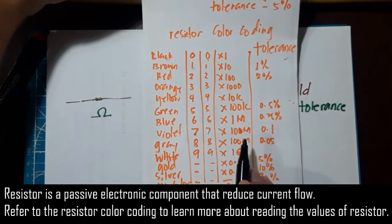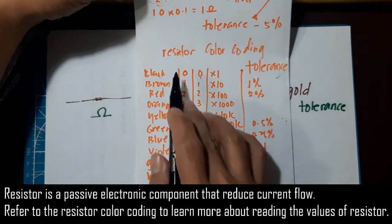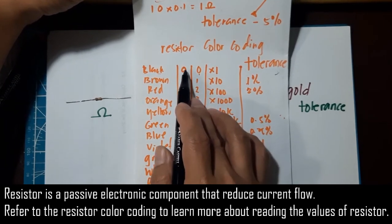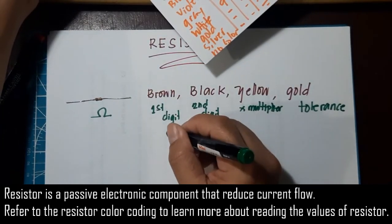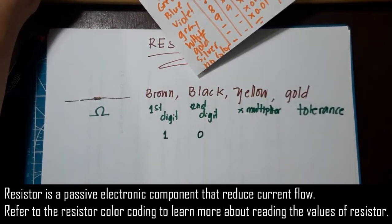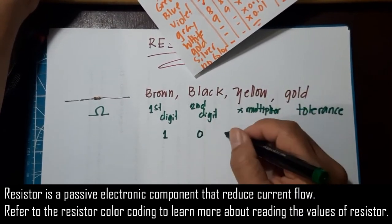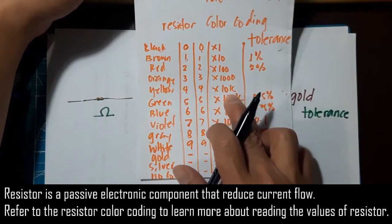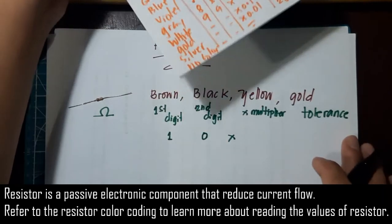Checking the resistor color coding, brown is 1, black is 0, and yellow is your multiplier, so that's times, what is yellow here? 10K, or 10,000.